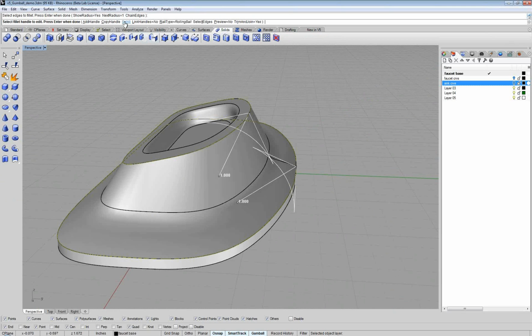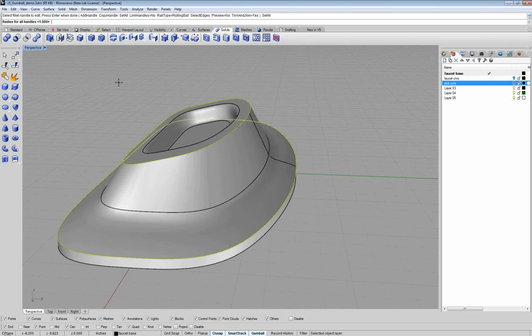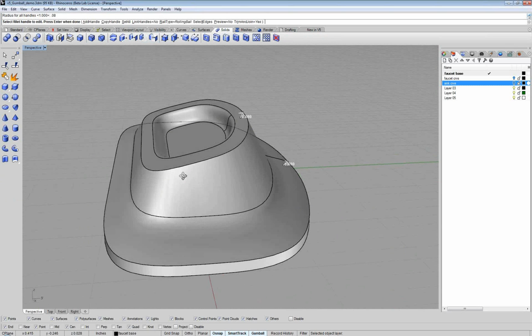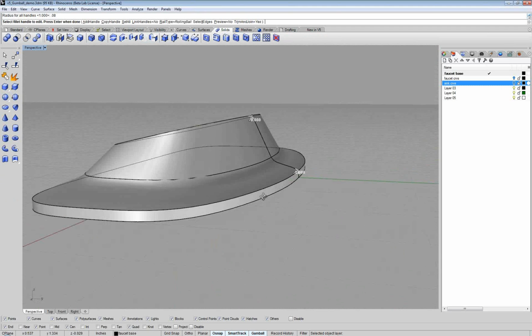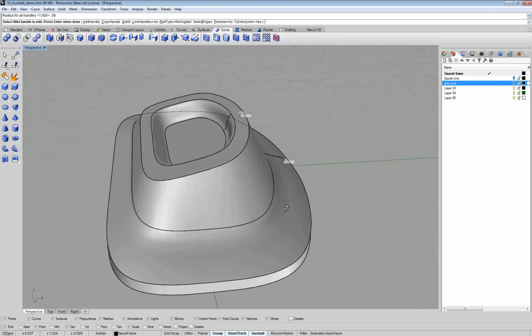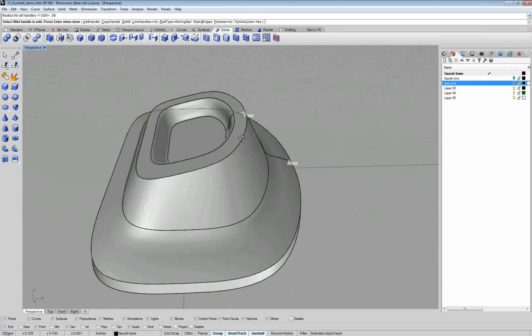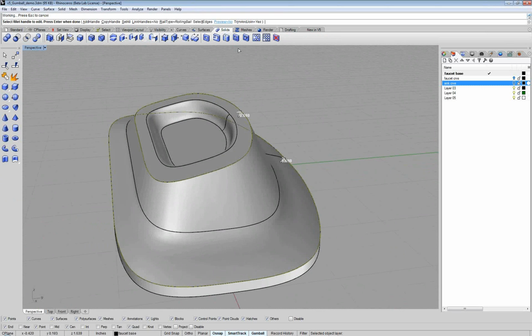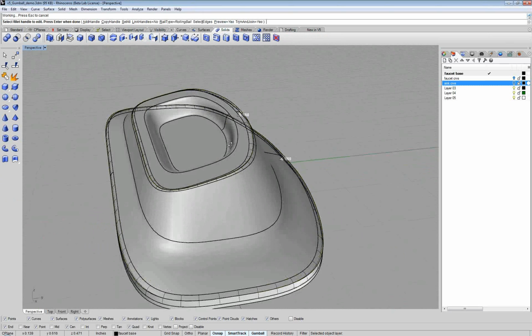So up in the command line I'll just click on Set All, and I'll type 0.08, and I can see that radius looks like it will have enough space to trim against the adjacent surfaces. And I'll click Preview and wait for your screen to catch up here.